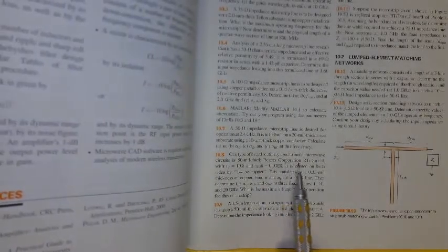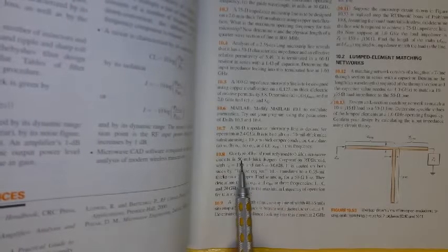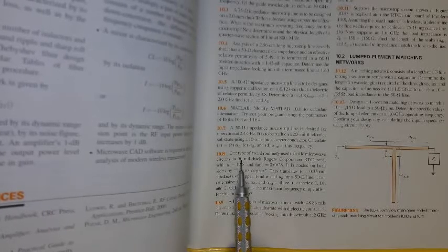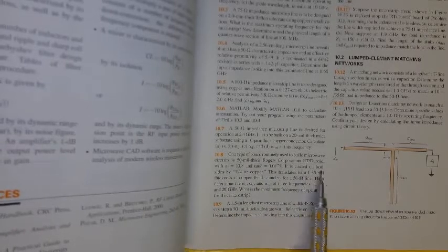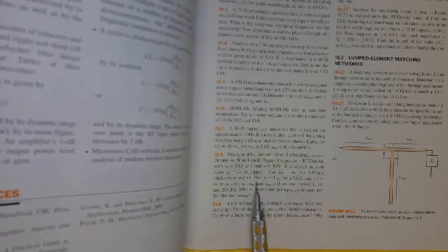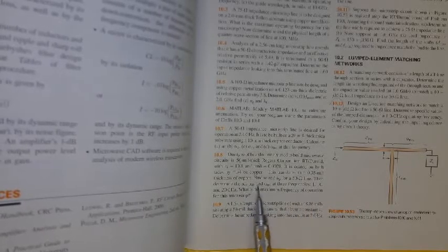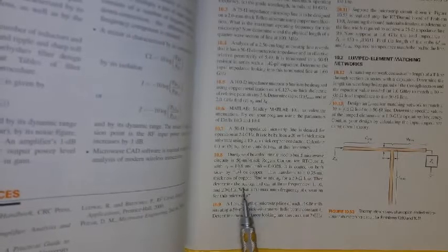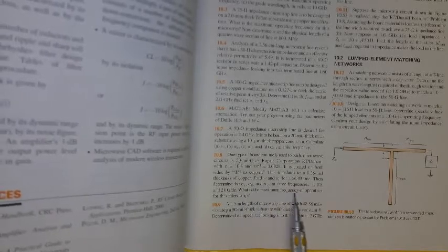This is manufactured by Rogers. They're pretty good about giving you samples if you ever want a sample. And so it's 50 mils thick, right? That's the thickness of the substrate. The dielectric constant is 10.8, right? It gives you some other parameters in here that you can use to compute the loss on there. So I just ask you to read that section. Read the section on loss. There is some attenuation as the wave propagates down the line, and Stu has a little section in there on that. Go ahead and read that.